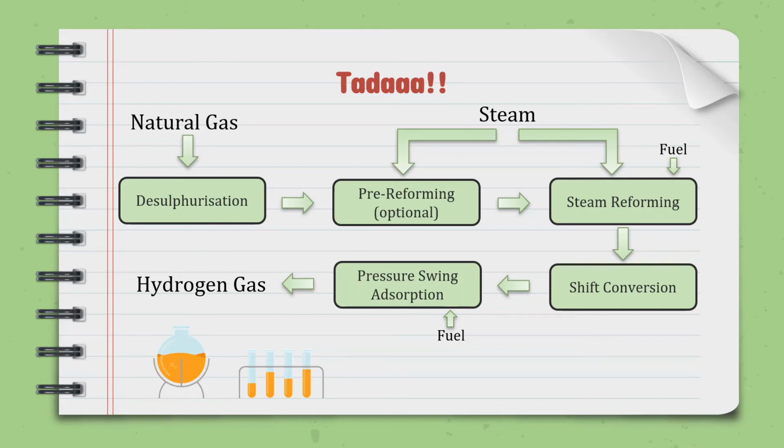which allows for more efficient reforming downstream. Then, steam will be released to react with the hydrocarbon in the reactor to form hydrogen, and then it will reform again to react with the same reactant. The next step is shift conversion, which is the reaction of synthesis gas with steam to convert carbon monoxide into a raw gas mixture, including carbon dioxide and hydrogen.